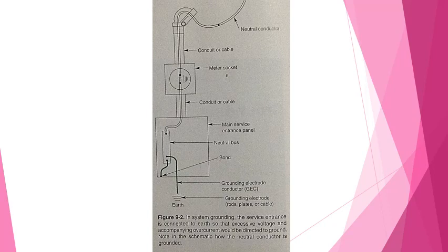Again, proper equipment grounding would carry this unwanted current back to the service panel, where it would cause the OCPD, overcurrent protection device, to open the circuit. Excess currents would go to ground. For this, see figure 9-3.